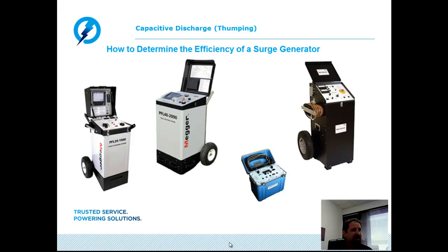The larger the value of capacitance within the surge generator, the greater the amount of available energy for discharge into the fault. The greater the probability of intersecting the characteristic flashover curve that we're going to talk about a little bit later, which is characteristic to a gap or in essence a fault. And the output of the surge generator, as I mentioned, is output voltage and energy.